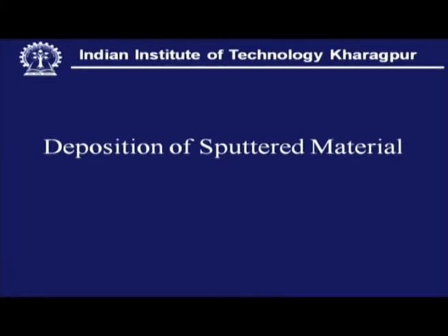Sputtering is ejection of the material, dislodgement of the material from a surface which we call in the language of sputtering the target. This is not actually the deposition process. In fact, the material or the surface which we need to coat or cover with a layer has to intercept this flux of material which will be ejected by the impingement of the energetic projectile, and this is actually the deposition process.